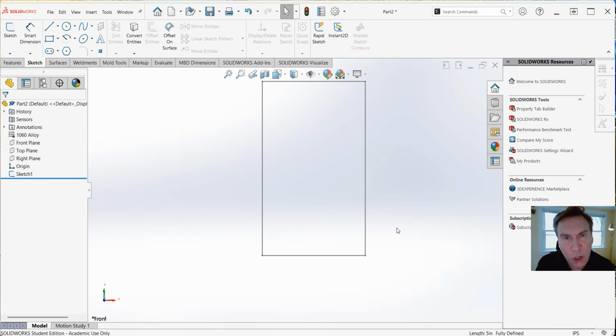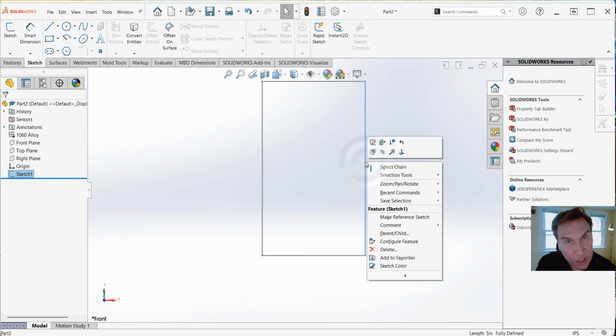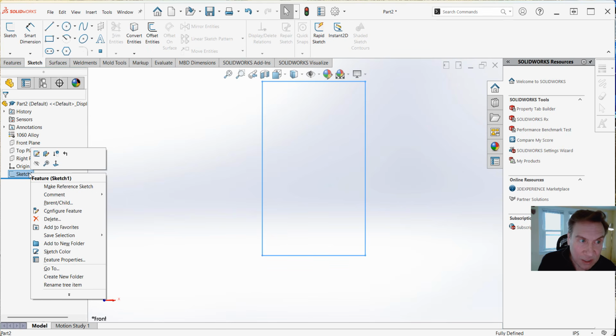Anyway, so I went ahead and I applied that. You could see it exited us out of that sketch again. You could either double click. If you're not able to double click on it to access it, and I've seen this happen, and I don't know if it's the mouse or the user, you could also right click, and right there is Edit Sketch. You can also right-click in the feature tree on the sketch that's listed there and click on Edit Sketch.